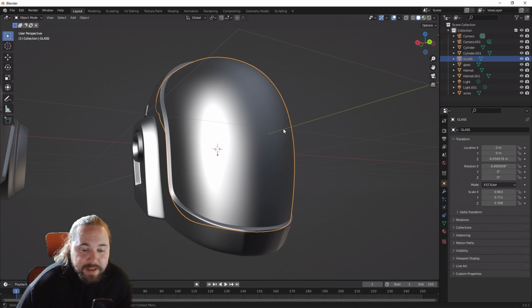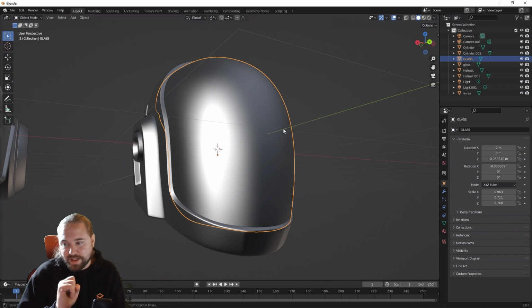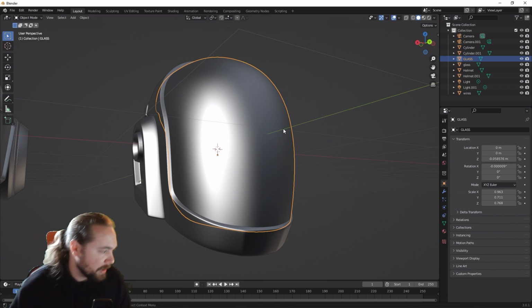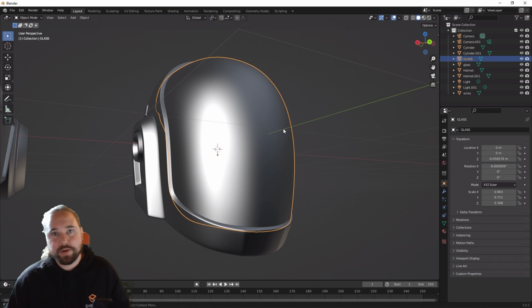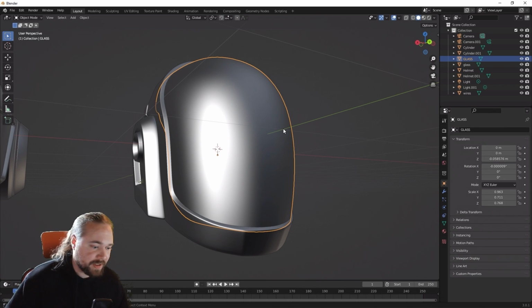But anyways, this warning message that Enscape oftentimes brings up regarding a maximum of 20,000 polygons, well, that's a warning message regarding the fact that usually you will bring in a custom asset into Enscape that you don't want to place just once in your scene, but probably a lot of times. Things like trees, bushes, people, cars, whatever.